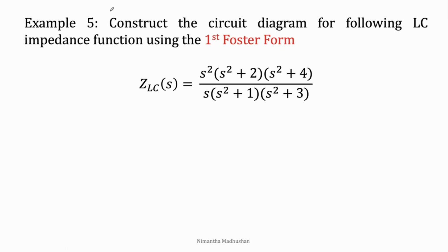Hello everyone. In this video, I am going to explain another circuit synthesis problem. This impedance function is for an LC network, and we have to construct the circuit diagram using Foster form. In Foster form, we use partial fraction expansion to construct the circuit diagram. First, we have to simplify this impedance function.